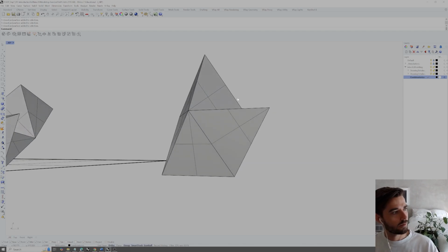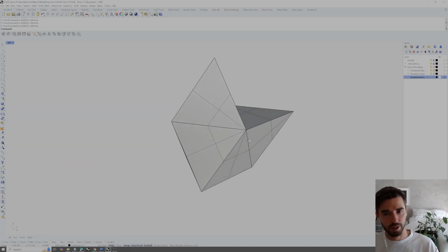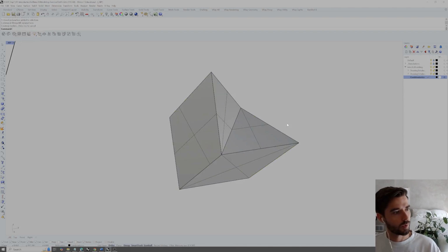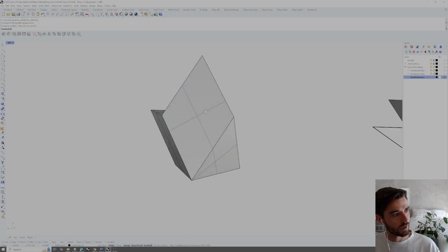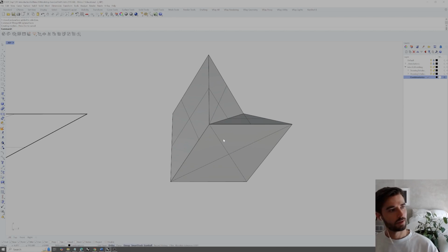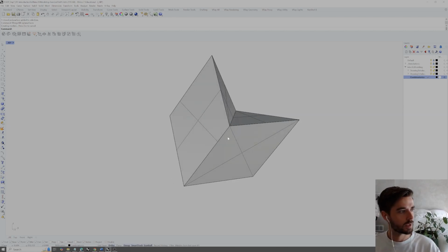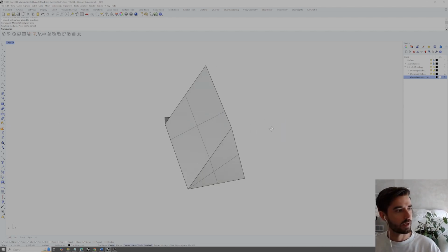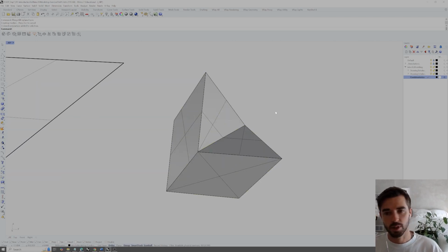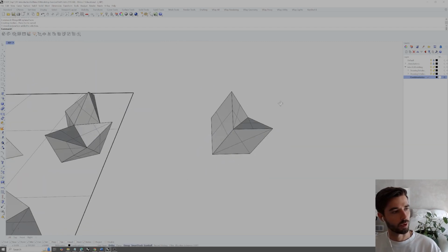And since we have certain faces that are already aligned, we can go ahead and clean it up with merge all coplanar faces. When we type that, it takes each of those faces that were aligned and makes one complete untrimmed face, at least in this case, that combines what were coplanar faces. So that's a good way to prevent the kind of messiness that often comes with repeated Boolean operations.